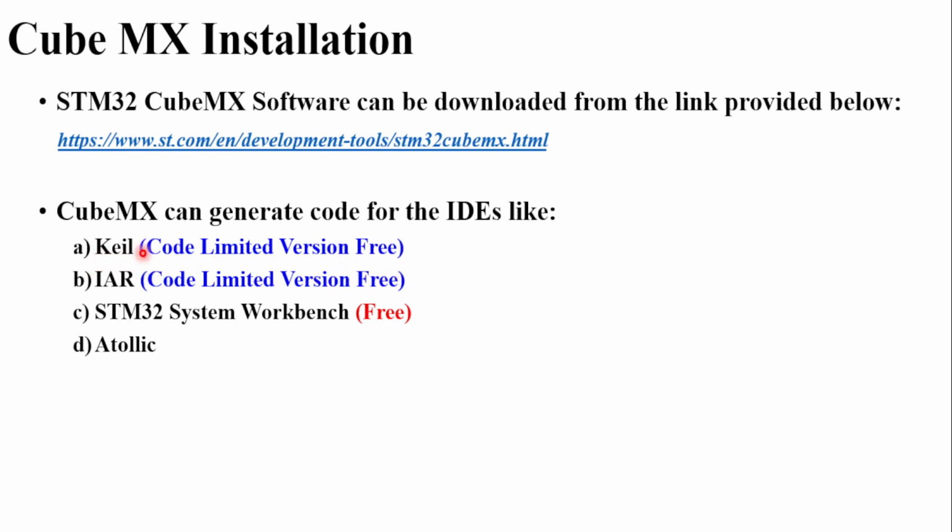If you are interested in working with Keil or IAR, remember in the free version, you can go for a maximum code size of 32 kilobytes. Otherwise, you can work with STM32 Workbench, which is free and is able to program up to the whole memory of the microcontroller, which is unlimited code size.